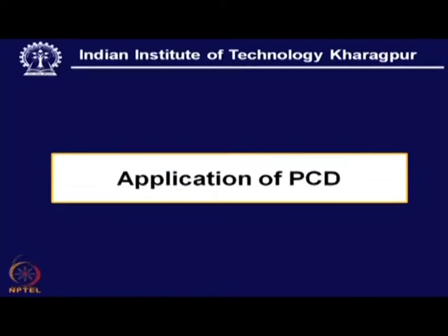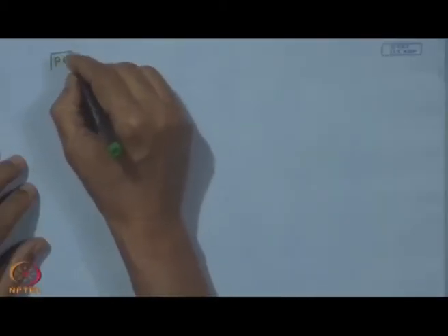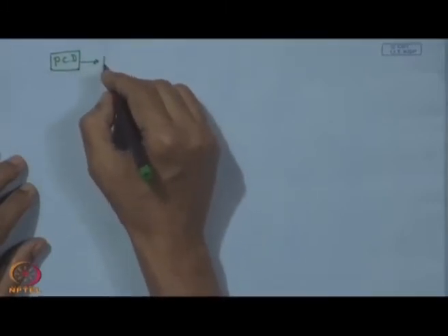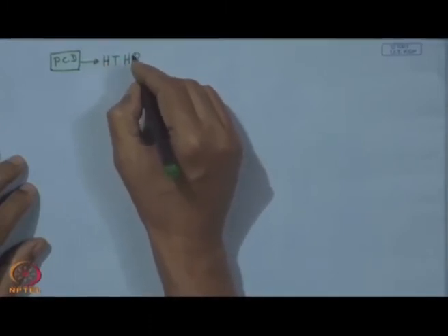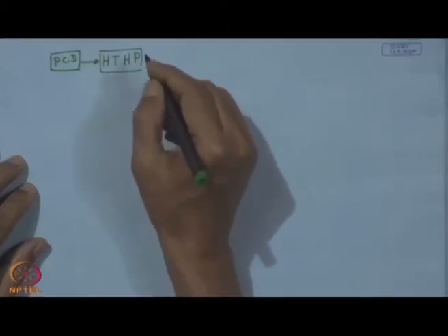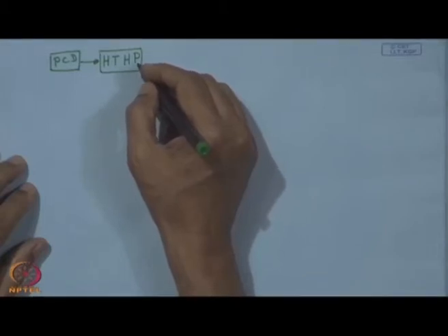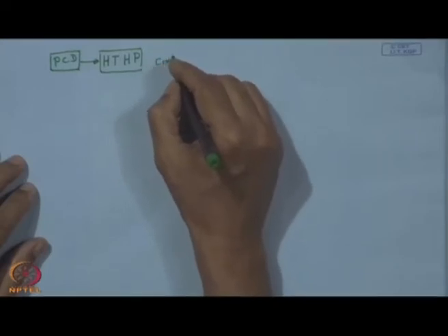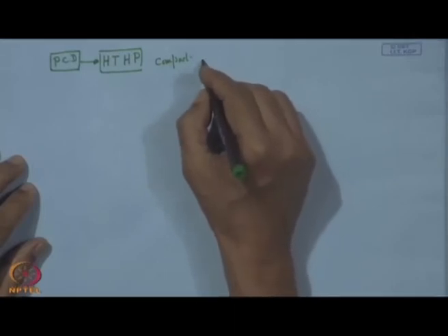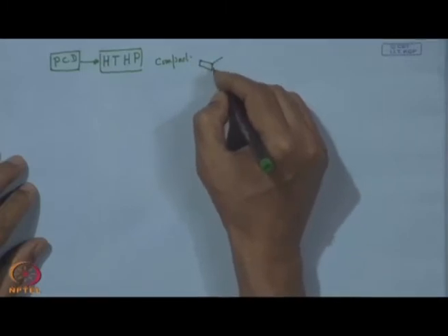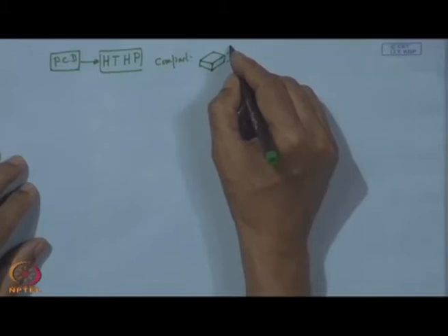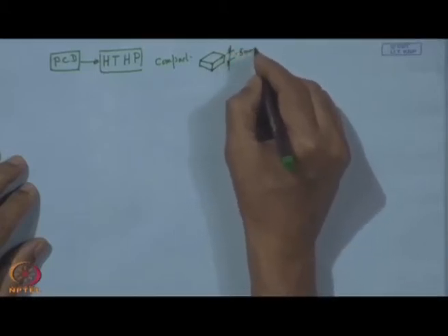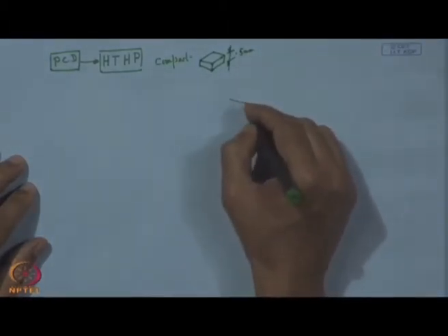Now, as a substitute for this natural diamond, later on the polycrystalline diamond compact came into being. This is actually the result of high temperature, high pressure technology. That means tiny particles of diamond are subjected to high pressure and high temperature to make a compact, and this compact can be in the form of a round bar or it can have a square shape, maybe around 0.5 millimeter thick, and that can be brazed on a carbide base.